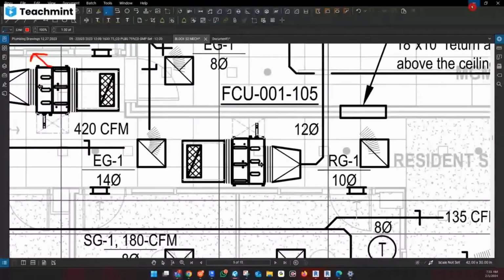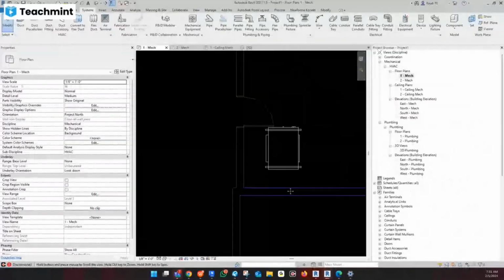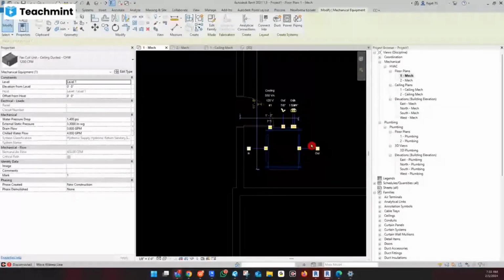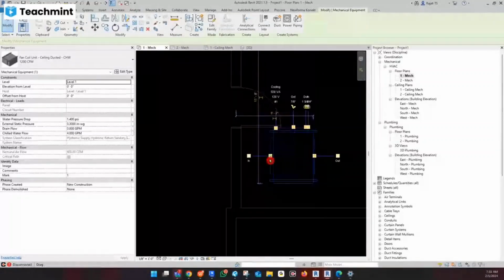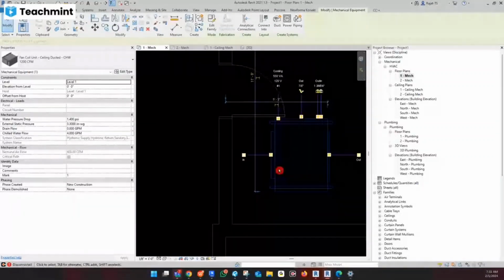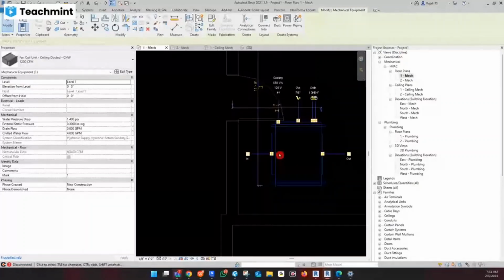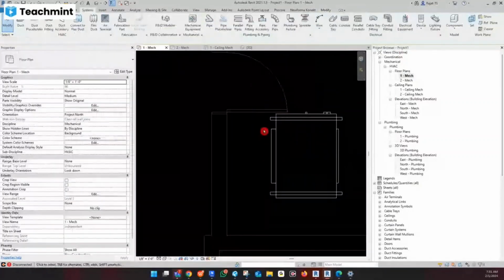So what happened? Again, there is a theory. Once we install the machine above the ceiling, noise basically happens inside the supply air system due to the fan vibration or something else. So we can use a flex connector here. The flex connector should be like this.